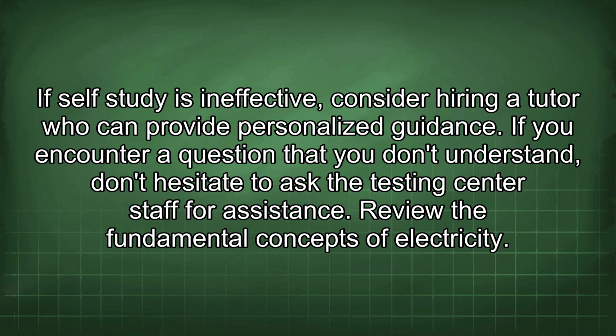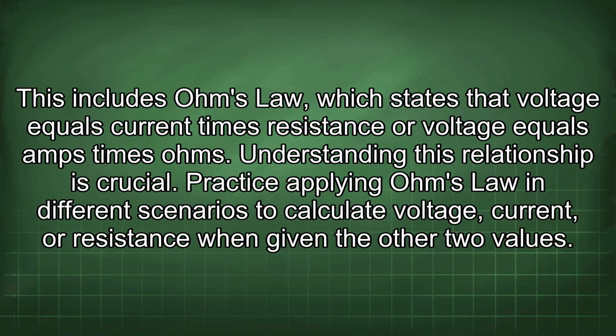Review the fundamental concepts of electricity. This includes Ohm's law, which states that voltage equals current times resistance, or voltage equals amps times ohms. Understanding this relationship is crucial. Practice applying Ohm's law in different scenarios to calculate voltage, current, or resistance when given the other two values.